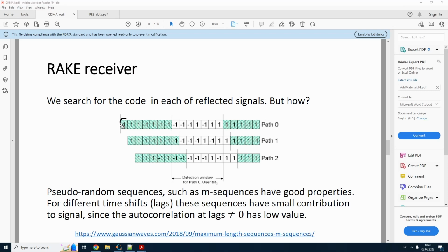So consider we have this sequence. This is our M sequence, and we also have some signal here, which would be -1, let's say like this, +1, and what we would do now is try to find where exactly this sequence is inside. So we are going to compare these two symbol sequences like this. The autocorrelation function, ACF, would be low, so this definitely isn't a match.